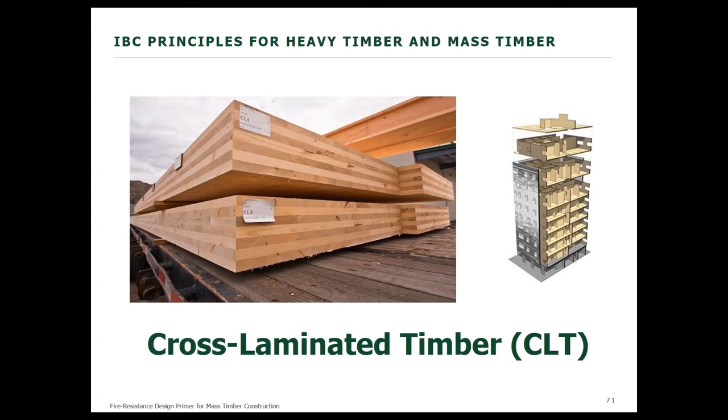So to summarize, basically, mass timber as a separate building system was really born because of one product, cross-laminated timber. Never before have we contemplated solid wood floor and wall sections being used in a similar manner as concrete walls and floors. CLT is typically dimensional lumber, 2x lumber, laminated in crosswise fashion, layer upon layer. There's an odd number of plies, 3, 5, 7, 9, to make a solid wood wall, floor, or roof panel up to 20 inches thick and 60 feet long.